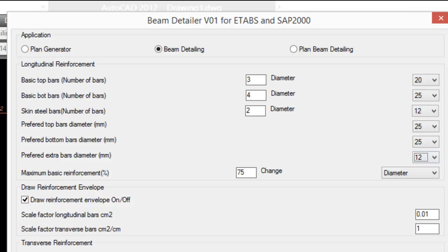This is just to save some weight. Okay, anyway, here you have the smart selection, as I call it. This is to control the basic reinforcement. As long as you don't know the amount of reinforcement yet, you can control it by assuming a ratio. This ratio is the ratio between the basic reinforcement you use and the required reinforcement.